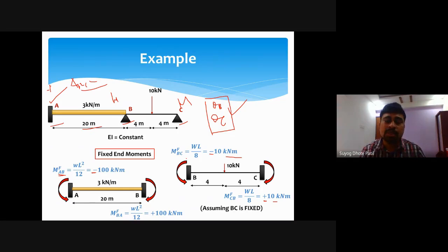One hundred percent, every time when rotation is possible, there will not be any reaction in terms of rotation, because it is free to move in the clockwise or anti-clockwise direction. So at joint B and at joint C, rotation is possible because these two joints are hinged. At a hinge support, rotation is possible but moment is not. Rotation is possible means moment is zero.